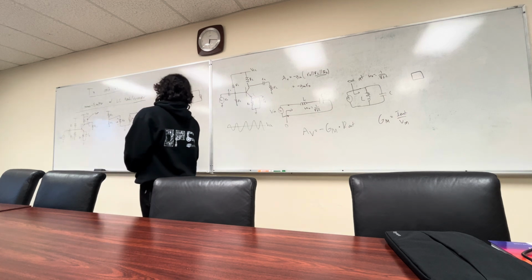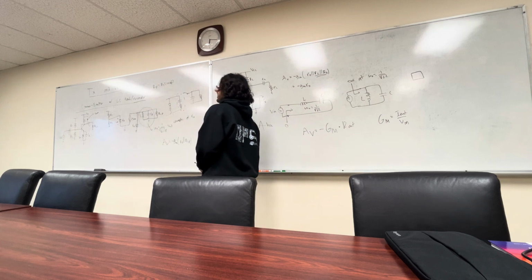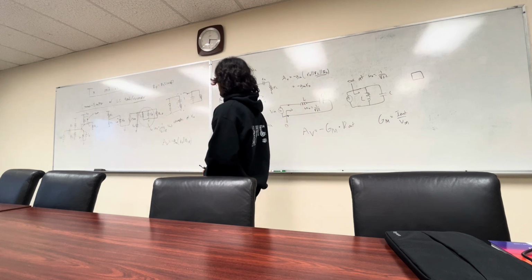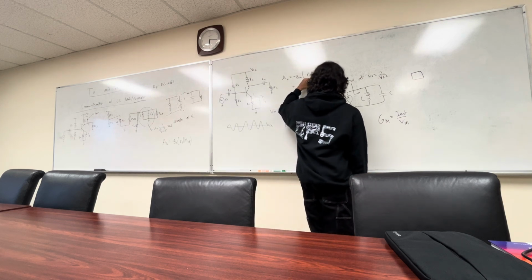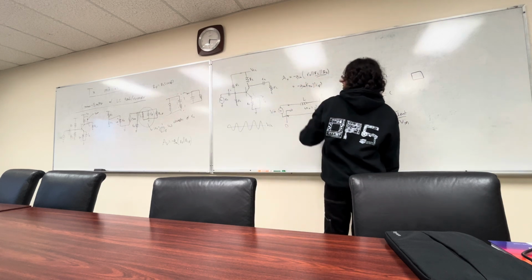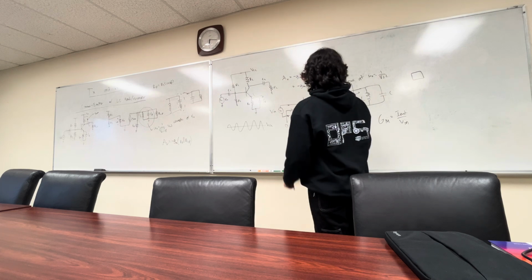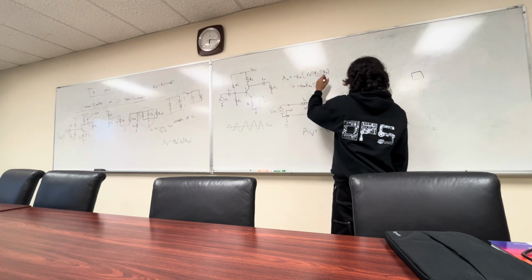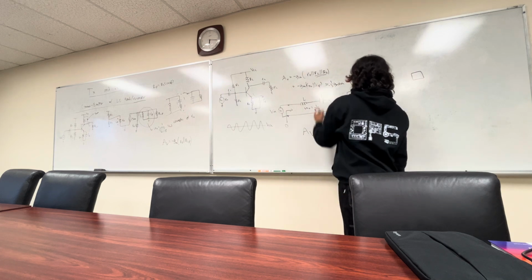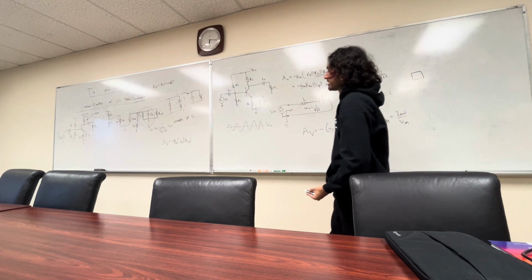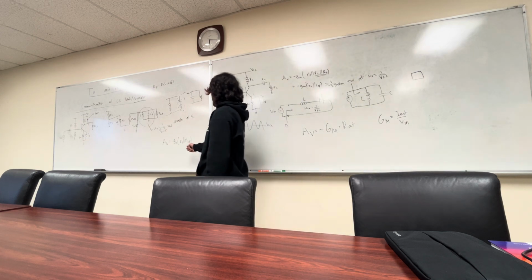Yeah, you can very well do an active load too. However, your gain is going to be negative gm (ro_n parallel ro_p), and of course, it's typically just going to be half of your gm ro_n, roughly. And why get half when we can make this pretty large?